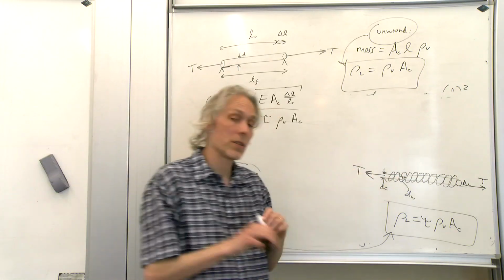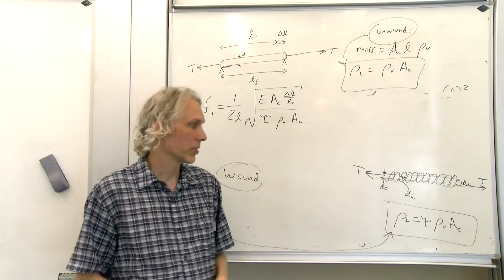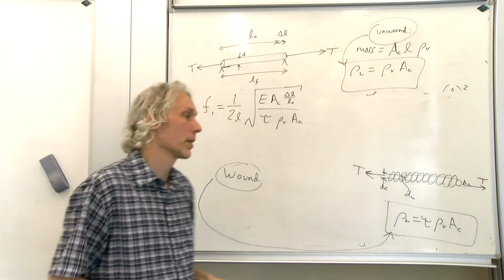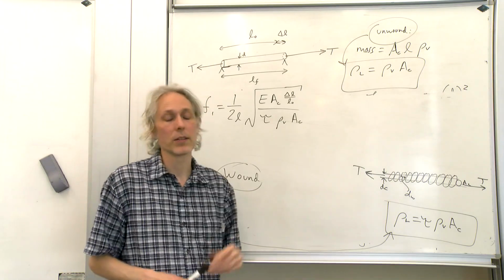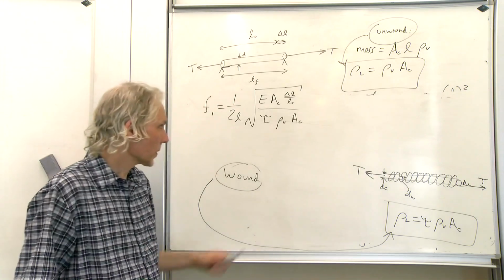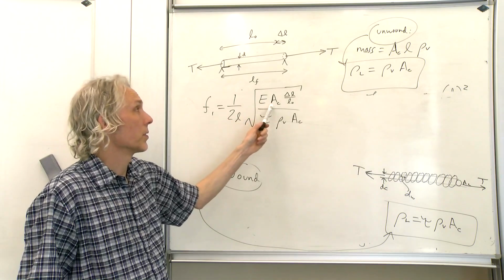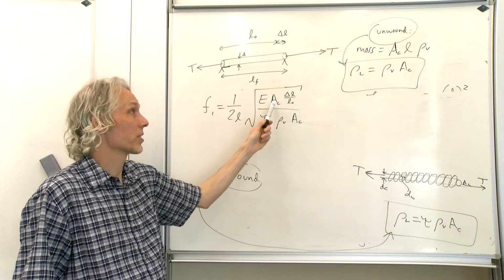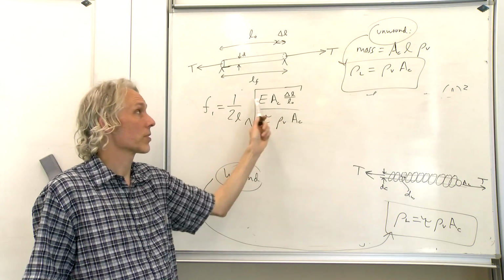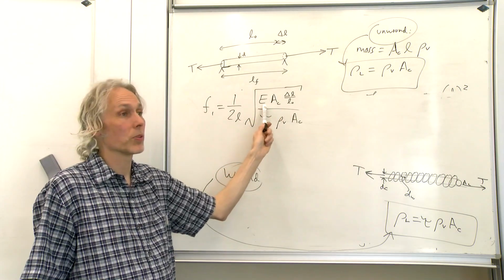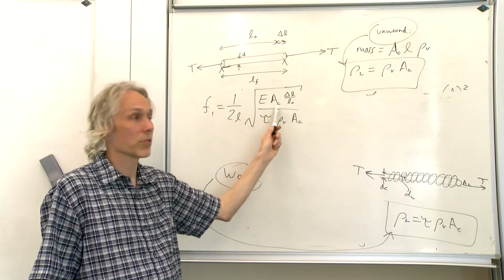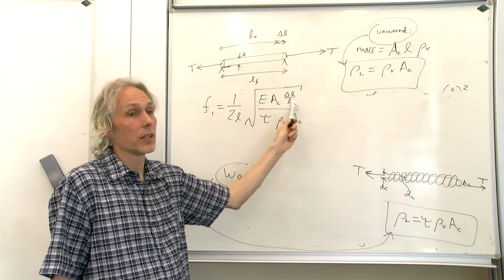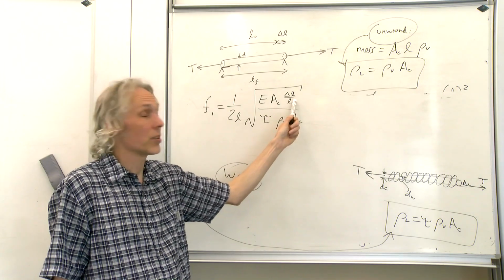Whereas the core is entirely responsible for the tension that we observe when we're playing a wound string, tensioning it and tuning it. So we don't have to take into account the cross-sectional area of the winding at all in the top half of this equation. This is the tension. Tension equals Young's modulus times the cross-sectional area of the core times the fractional elongation here, the engineering strain.